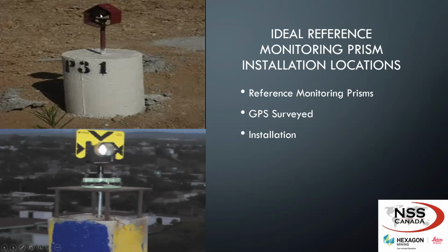So I need northing, easting, and elevation. That way, when I'm monitoring, the total station can reference itself off these prisms that have not moved. So you want them outside of the working project, which I'm going to go into next. So, like GeoMos monitoring stations.